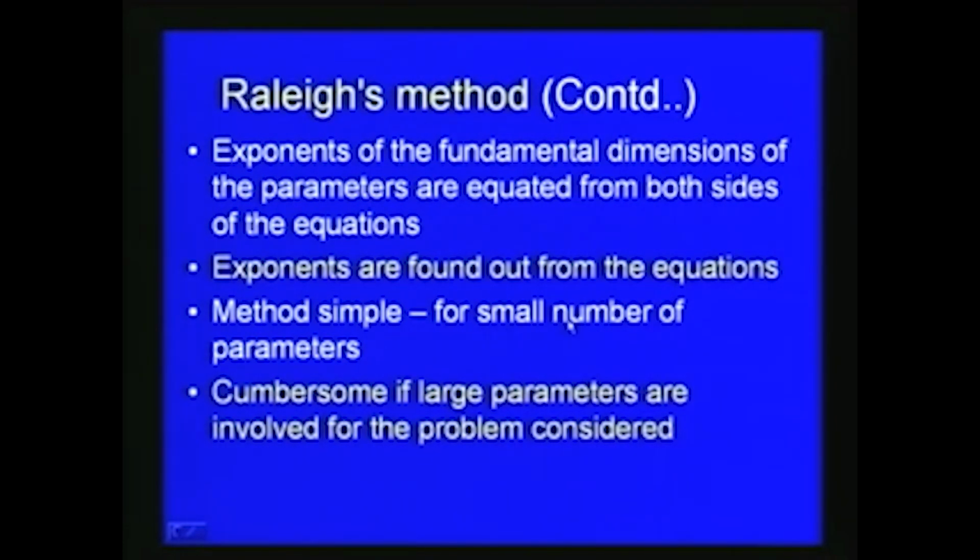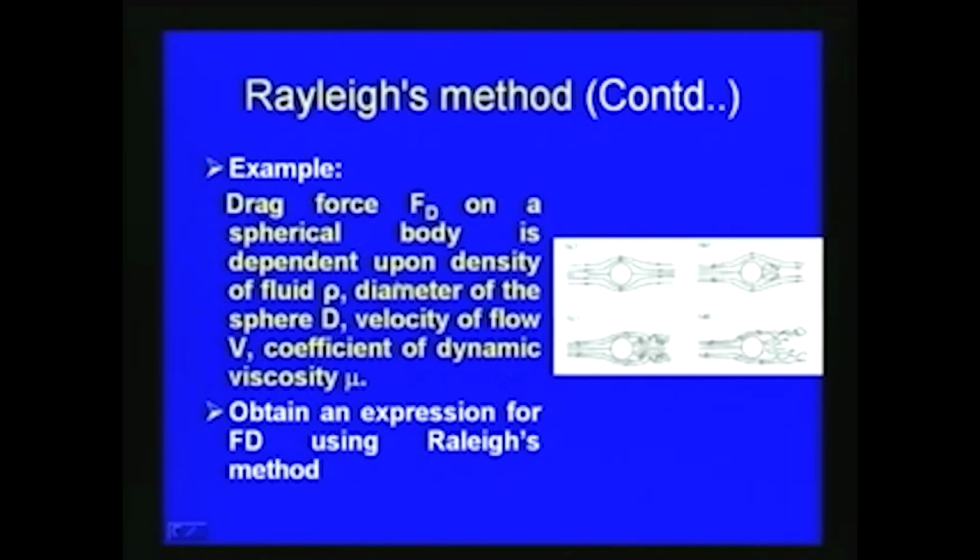To further illustrate Rayleigh's method, we will discuss a typical problem. The problem is the drag force. To find the drag force Fd on a spherical body, it depends upon the density of the fluid, the diameter of the sphere, the velocity of flow, and the coefficient of dynamic viscosity mu. We have to obtain an expression for the drag force using Rayleigh's method.